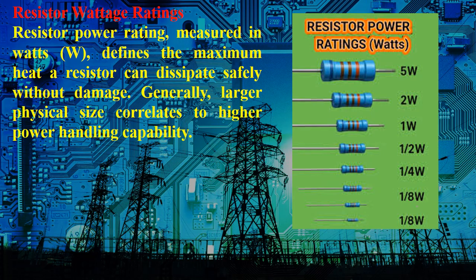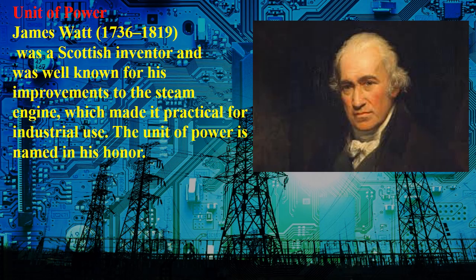Resistors convert it into heat, light converts it into light, motor converts it into motion. So resistor power rating measured in watts defines the maximum heat a resistor can dissipate safely without damage. Generally, larger physical size correlates to higher power handling capability. So when you see a big resistor, that means its power rating is greater. When you see a small resistor, the power rating is smaller.